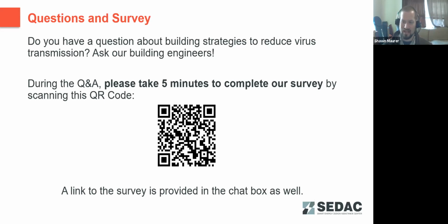Buildings in general, even laboratory buildings with high exhaust rates, are going to be positively pressurized to the outside to prevent drawing in contaminants. So if your building is negative, there should be a tweak to the air handling system to increase outside air introduction to the space, to bring it back to a positive rate. You can have rooms in the building that are negative relative to other rooms, but the building overall should be positive, even if you've got laboratory ventilation and things like that.